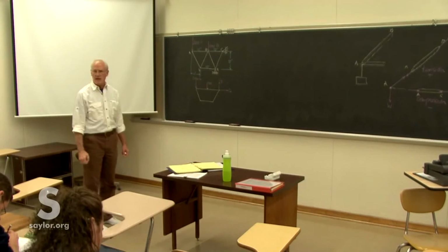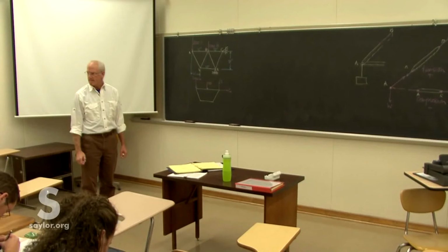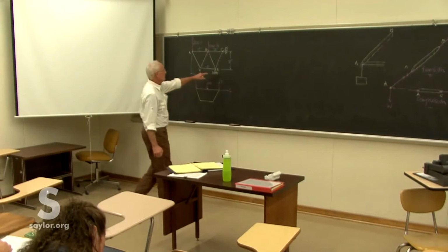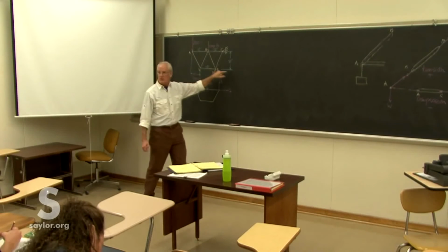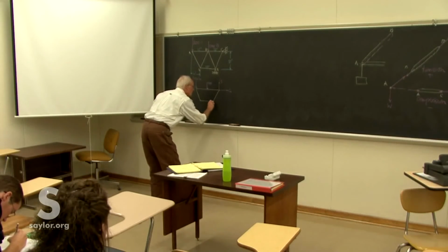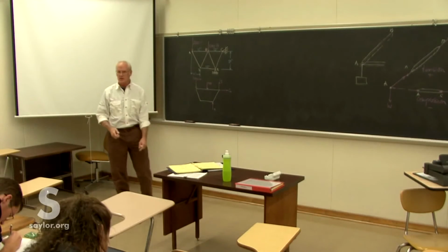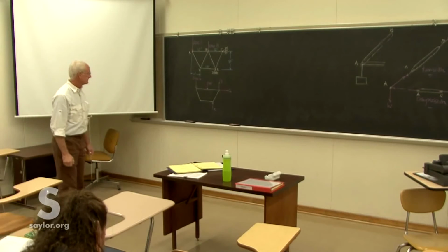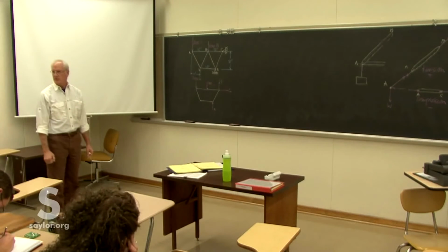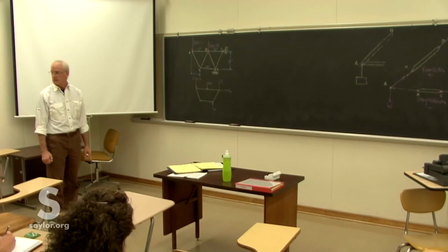What about at E? Just an upward force. Because of the rollers, there's no transverse support. There's only the support there. So we don't even have to call it EX and EY. It's just going to be E. And we can figure out what those are. Who wants to do CX?